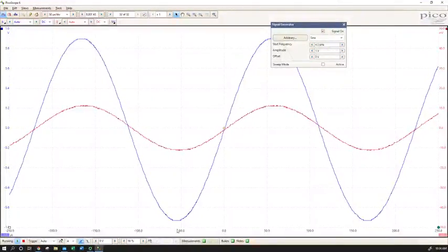So now I have around a 0.6 Henry inductor, and I have a 1/4 Henry inductor. I could do the same thing for the secondary on this transformer, and it's very likely that I would get a lower value for that inductance, simply because we know that for a step down transformer, the secondary would have a lower number of loops, and that would give me a lower inductance. I would have to refer to my step up, step down ratio for this transformer to get an idea, or I could just flip it around and repeat these measurements.